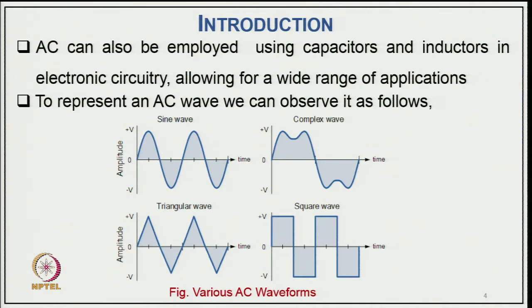If you look into the phenomenon according to Faraday's law of induction, you have to go through derivatives as well as integration. If you take the derivative or integral of the other three waveforms, the waveform gets distorted, and you will not get the same RMS voltage and current through the transformer.